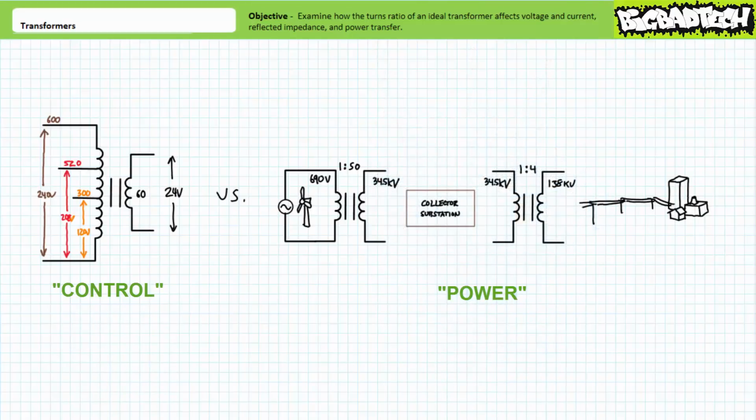Don't for a moment equate step-up transformer with the term power transformer, because one needn't look any further than the transformer at the distant city being asked to step down the massive amount of power on the 138 kilovolt transmission line to a level more appropriate for distribution to their industrial and residential customers. The step-down transformer at the city would also be classified as a power transformer, since it's changing the electrical characteristics of massive amounts of power for the purposes of transmission.